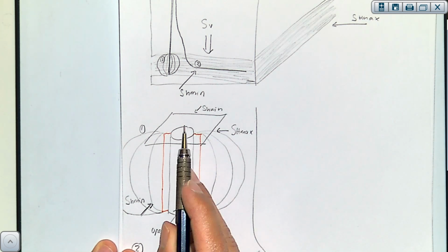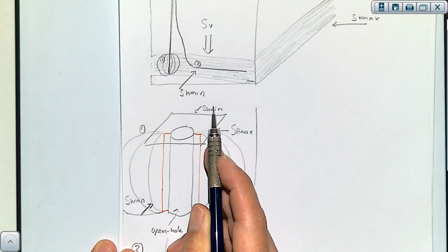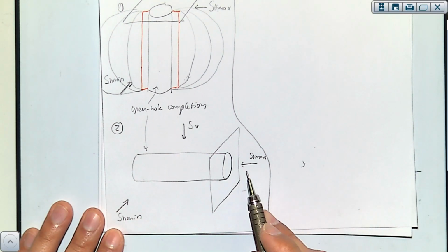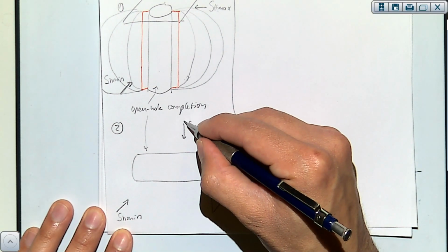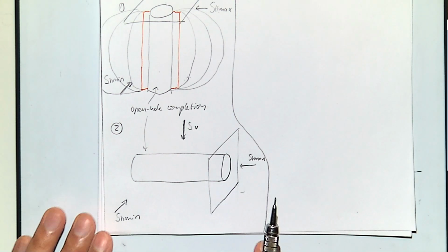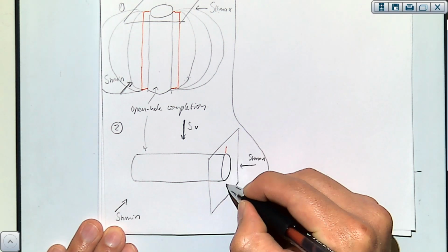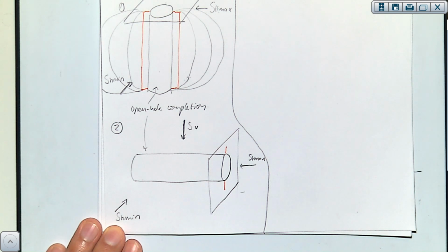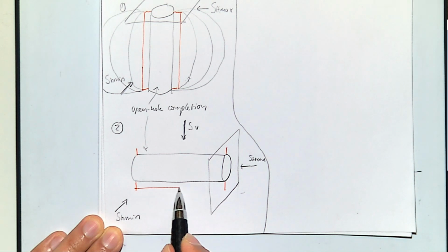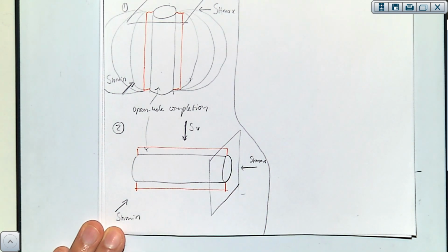Therefore, the maximum compression is going to be here, the tension is going to be there, because this one is different than that one. Well, the same thing over here, we're assuming that this is normal and that SH max. And again, if we extend this in 3D, this will look like these planes around the wellbore.